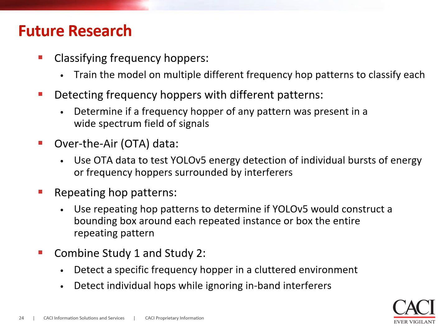It would also be interesting to combine both methods of detection, detecting a specific frequency hopper in a cluttered environment and then detecting each individual burst of energy of the frequency hopper while ignoring in-band interferers.